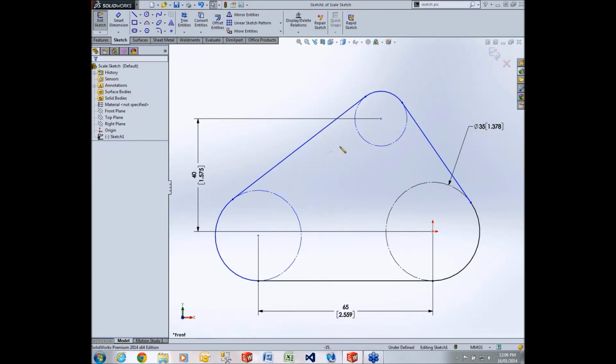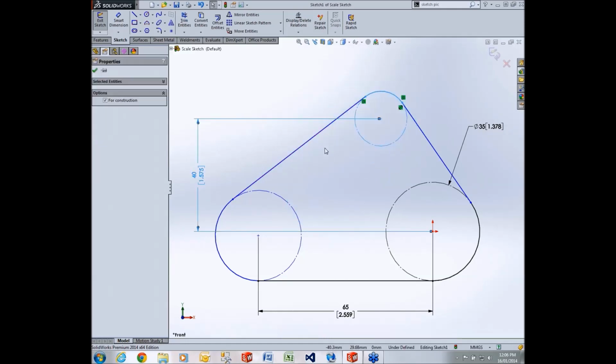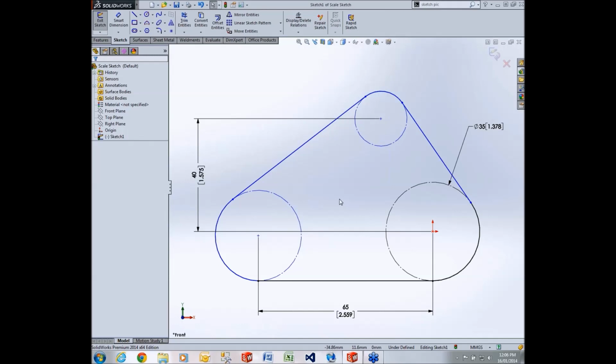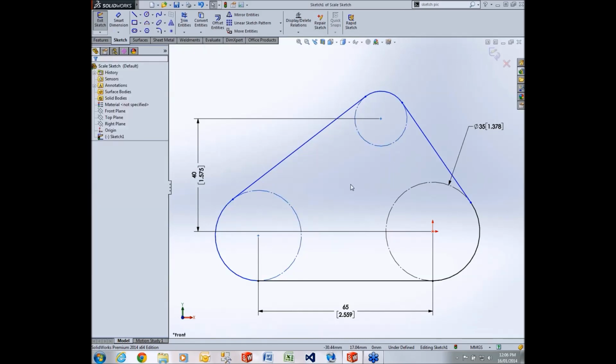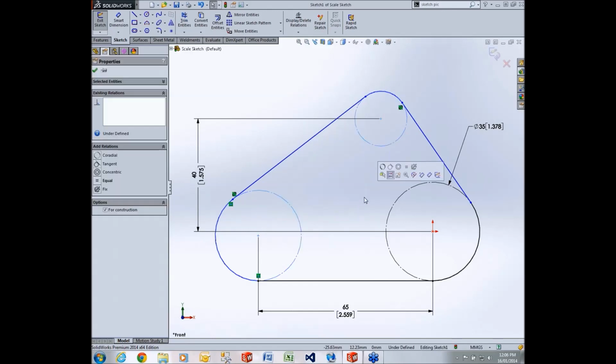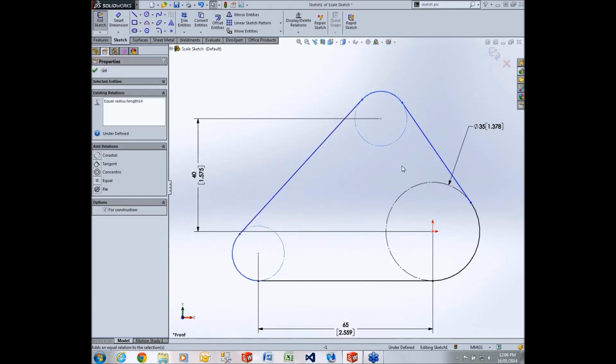What that allows me to do is to draw an area out, and it will select everything contained in that area. But again, it still behaves the same way as our box selection. If I go the other way around, so anti-clockwise, it turns green, and anything touching or crossing or completely inside the lassoed area is selected. So this is a much faster way for us to select these two circles. I can just do a lasso that touches the two circles there, and I can make them equal.